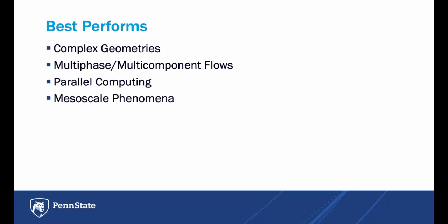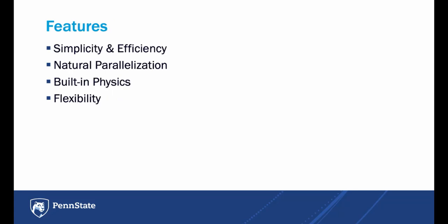For the best performance of the Lattice-Boltzmann method, it excels in porous media, microfluidics, and flows with intricate boundaries due to its simple boundary handling. It's ideal for simulating bubbles, droplets, or emulsions such as oil-water systems. It thrives in high-performance computing environments due to its local grid-based operations. It bridges micro and macro scales, making it perfect for systems like colloidal suspensions or biological fluids.